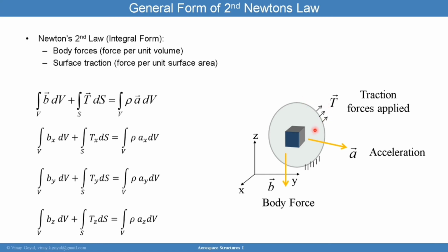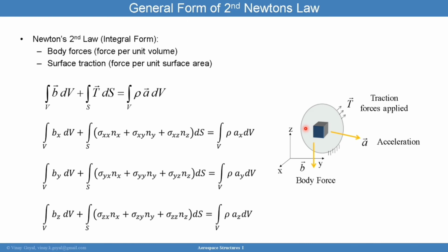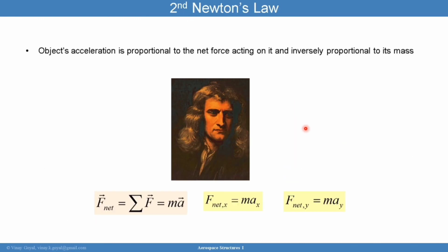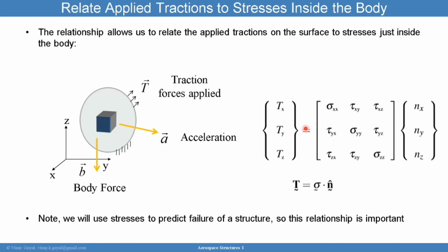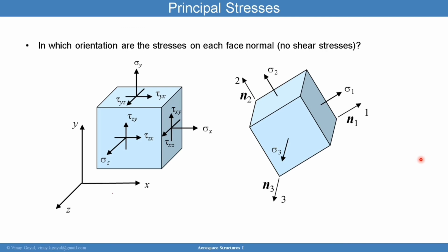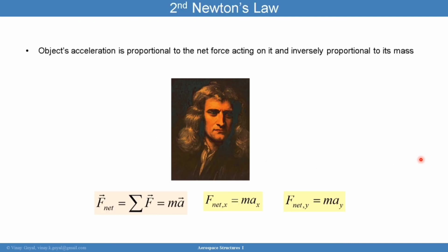Now I'll pause the video to see if you can remember how to relate tractions to stresses. And I hope you got it right, because to do that we use Cauchy's relationship. If you recall, in Cauchy's relationship, we relate the tractions to stresses using this normal quantity. So I can then expand on that and use it.